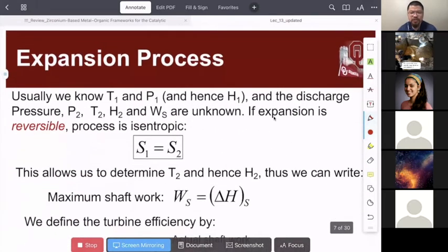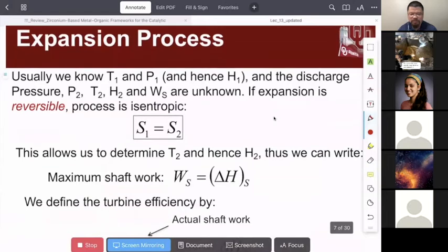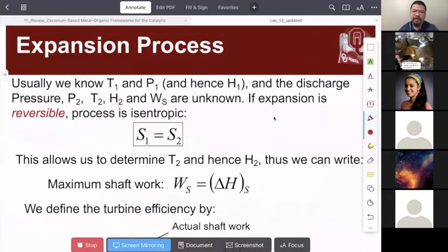So what do we actually achieve from there? Well, now if you include the entropy definition, ds is defined as a small amount of reversible heat versus the temperature. So we have this reversible for the Carnot cycle, right? Here for the turbine, we are still assuming this is a reversible process. And on top of that, this is the adiabatic process.